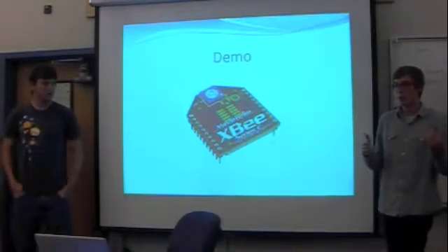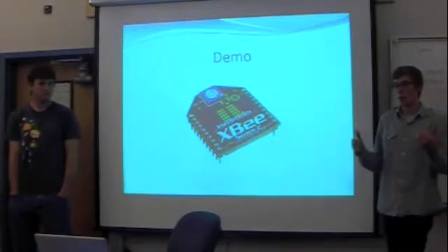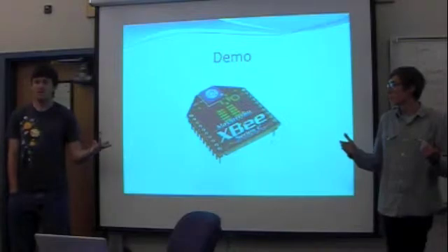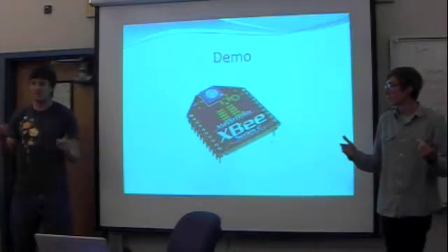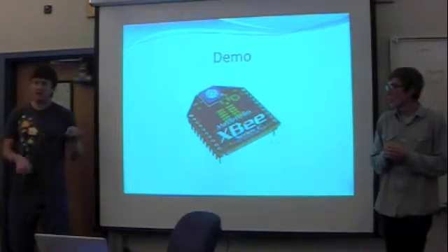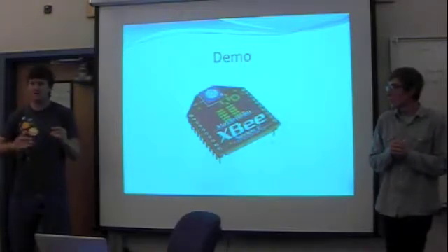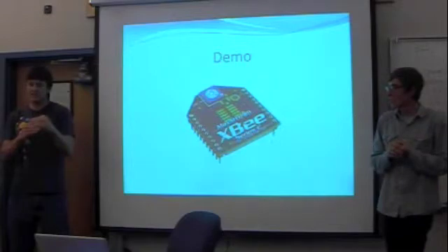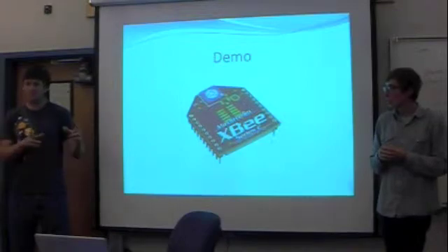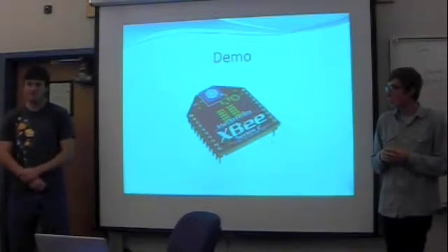For some reason, one of the buffers was full and not waiting for data. But that was only when you tested it with one board by wiring the UART out to the UART in, so you can send a message and then receive it. The problem was you can't send and receive at the same time with the UART. So if you sent too long of a message, you couldn't receive part of it with one board, but with two, it's not a problem.